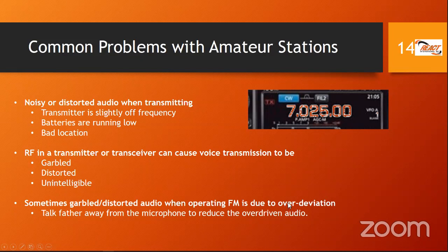Remember we said, with FM, it actually modulates the frequency. Well, if you are too loud into your radio, shouting in your radio, too close, and your audio gain, for example, on your microphone is high, you might be over deviating or over driving your radio. You may be speaking too loud. So one of the techniques, and this you'll find in your question pool as an exam question, that you can use is to talk a little further away.